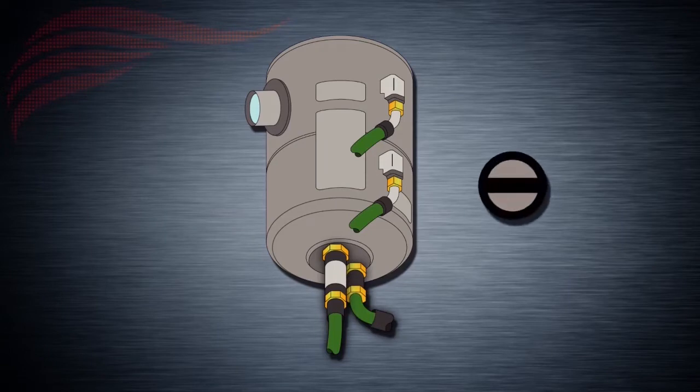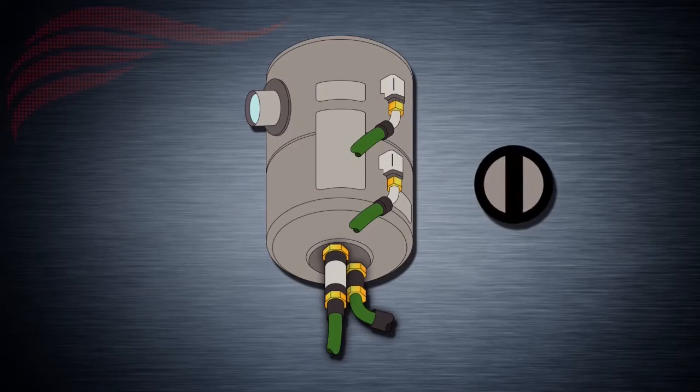There is a shut-off valve between each reservoir and its respective engine-driven pump that is triggered by pulling the corresponding engine fire switch. This valve shuts off hydraulic fluid flow from the reservoir to the engine-driven pump.